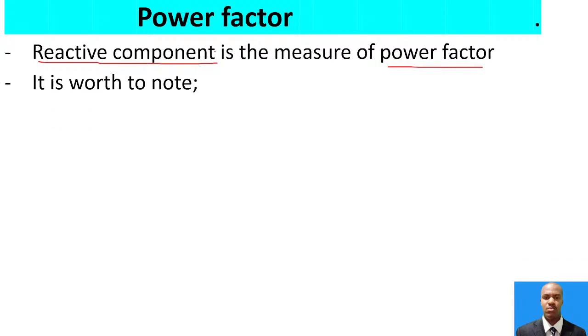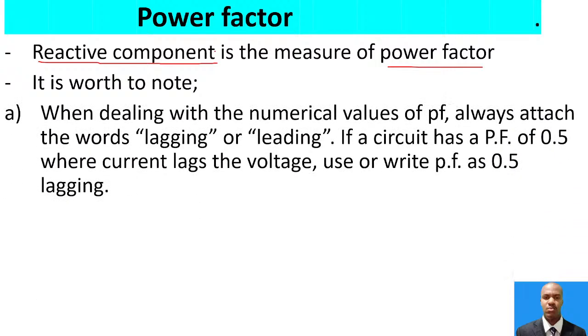So it is worth noting that when dealing with numerical values of power factor, always attach the wording lagging or leading power factor. So it is lagging for inductive circuits or loads, it is leading for capacitive circuits.